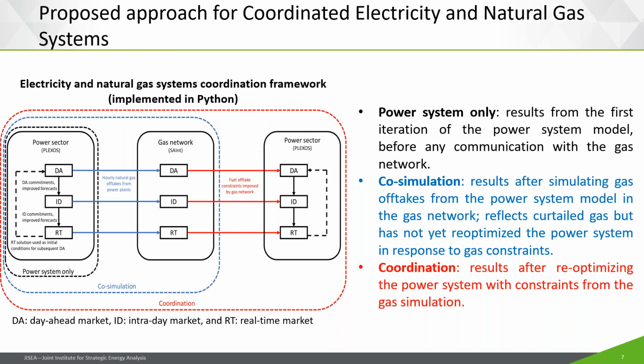And so in the day ahead unit commitment, you say whether those plants are going to be on or not. You can then, in the intraday time period, so this may be 4 to 6 hours ahead of real time, revise some of those for some of those plants, perhaps not a nuclear plant, but perhaps for a combined cycle natural gas plant. And then in real time, we can adjust the actual set points of each of those generators. And we do this to try to minimize the operational cost of the power system.